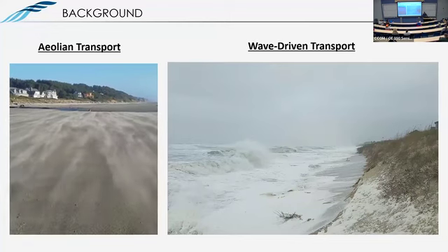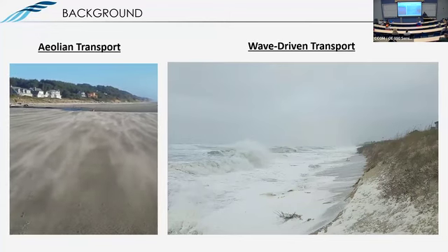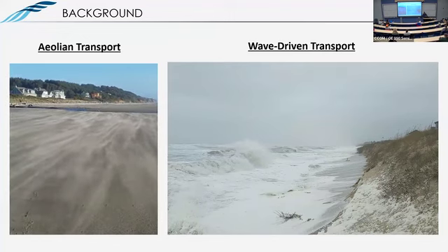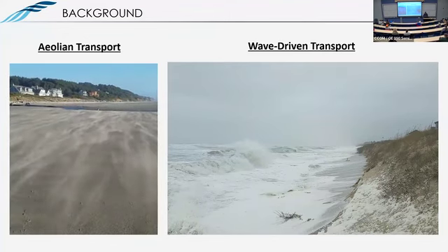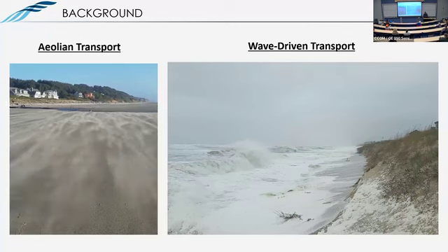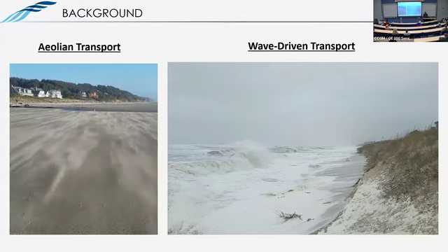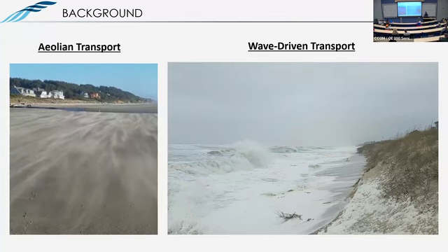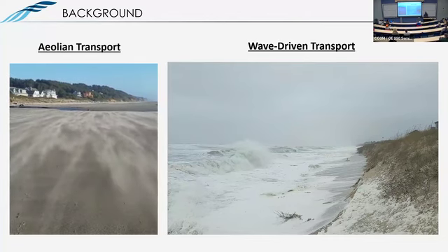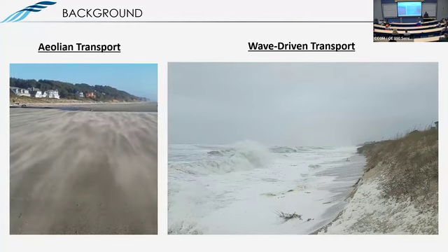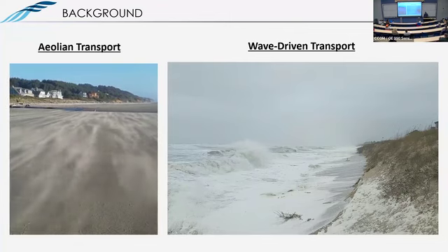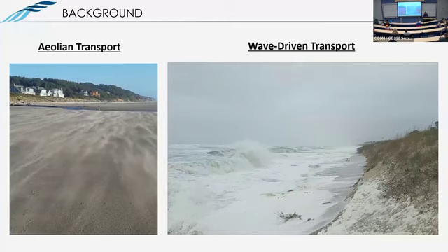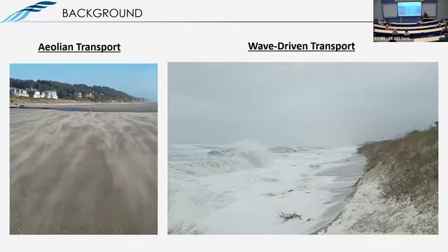Honestly, a lot of the invasive species have the most internal biomass in the dunes, but those are the species that, from a coastal resilience point of view, may make good sense for stabilizing your dune, but from an ecosystem services perspective would be really bad. So there's never one right answer here about the role of vegetation, but pretty much in all these projects, if you want to stabilize a dune, you can't just leave it as a sand pile, it will blow away. You need to have something that causes spatial sediment transport gradients to stabilize it. That's either going to be from vegetation or from sand fencing. So one of those is always incorporated into these projects.